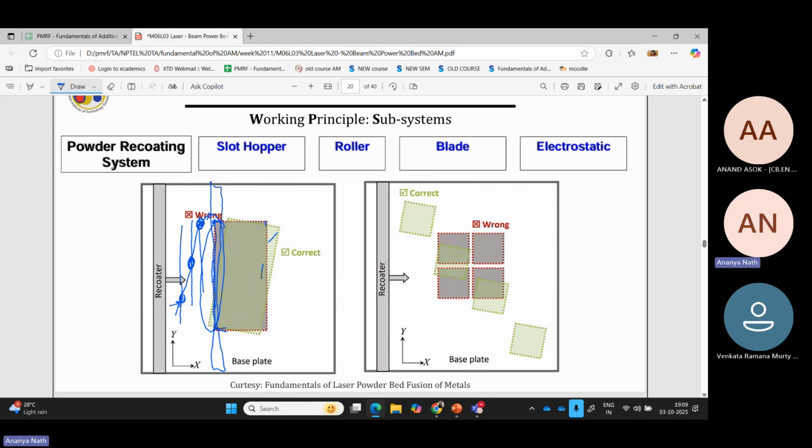If your recoater blade is a ceramic blade, it can get ruptured. It can get broken as well. If you have a soft brush, then it's better, but still your brush tips may come out. So that's why this tilted position is better. Also, it's not very recommended to have a very sharp corner.